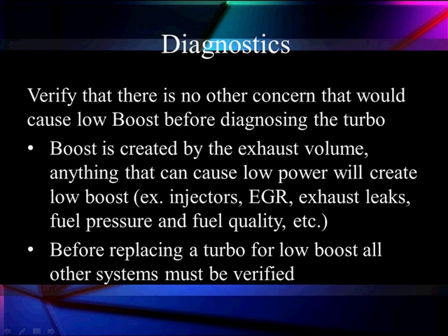We have to spend some time talking about turbocharger diagnostics, and it's a little bit of a complex subject, so let's make sure we verify there are no other concerns that would cause low boost pressure before diagnosing the turbo. Boost is created by the exhaust volume, which is a function of the amount of expanding gases we get from combustion. Anything that will cause low power, low combustion, will create low boost. For instance, defective injectors, EGR, exhaust leaks, fuel pressure problems, fuel quality problems.